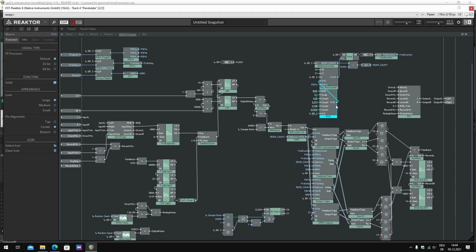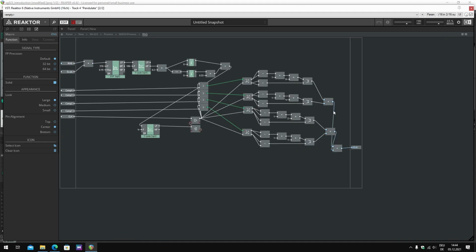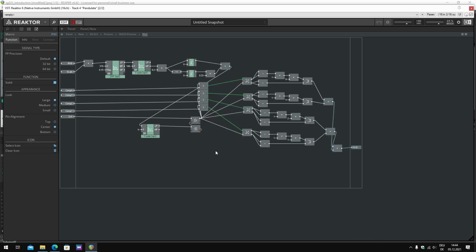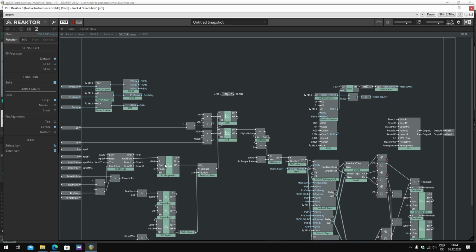Oh yeah, then we have all the modulation, which is based on a modulation counter, and there's a random number generator, which is also a bit weird. As you can see, the input signal in here goes to several places. We already had the mono signal that goes to the reverb path. We have the direct signal for the left and right outputs, and then we have this RND signal, which is used as the input for the random number generator.